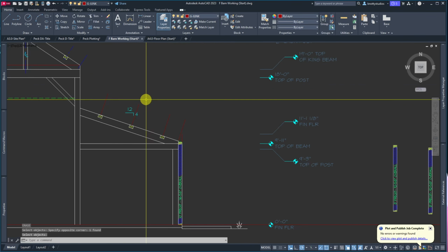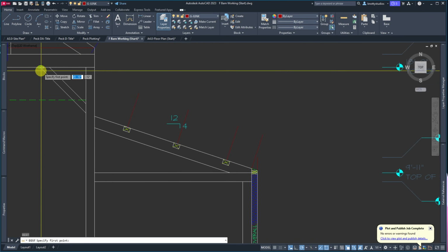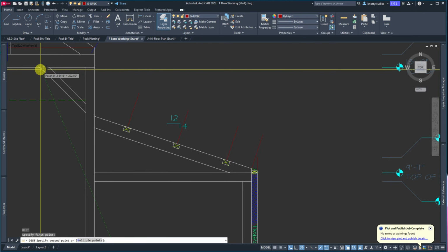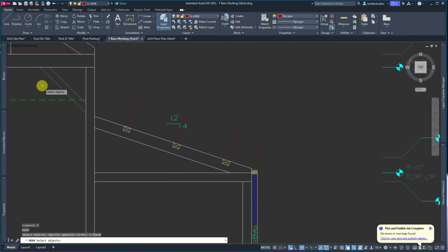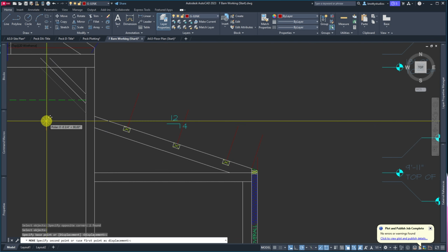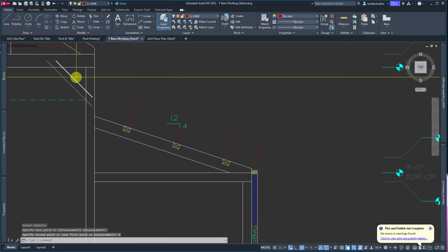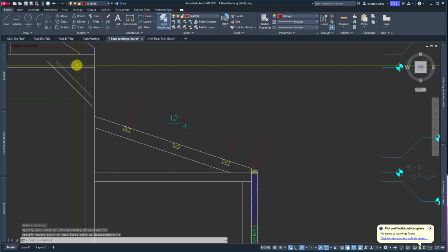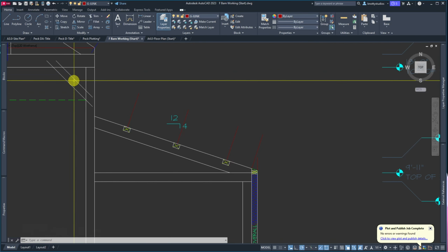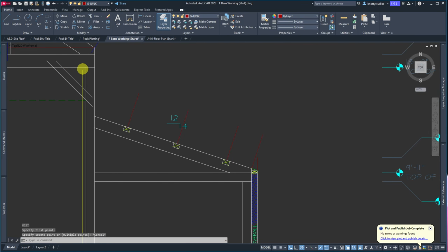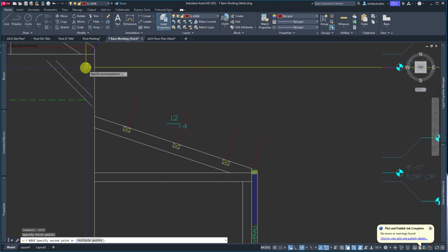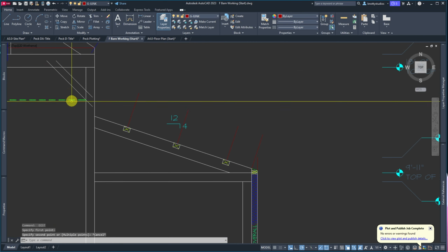And I'll get rid of that. So if I check this distance from here to here, and if that's 3 feet, it's 3-6. So I'm going to move this up 6 inches, and I'm going to move it over 6. And that's getting pretty small, but I think he's working on trying to make sure that this door fits in here. So the distance from there to there now, oh, it's 2-6. And the distance from here to here is 2-6.